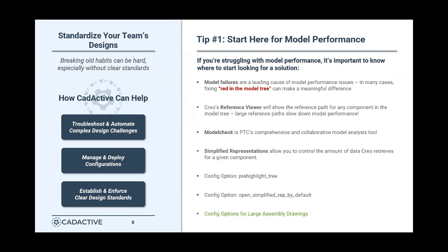There's another default rep that I want to talk about, but before I do that, a user-defined rep, like Phil had mentioned earlier, would be where we are explicitly going in and deciding what to load into session and what not to load. He used nuts and bolts, right? That's one example. What I want to talk about is what a lot of people would refer to as an empty rep. This is really common for people to use whenever they're working with really large, massive assemblies, right? You have an empty representation that just excludes everything.